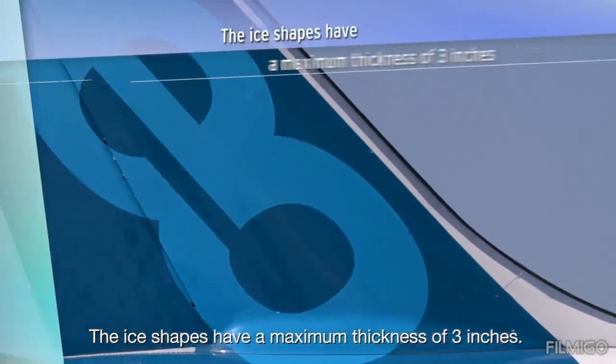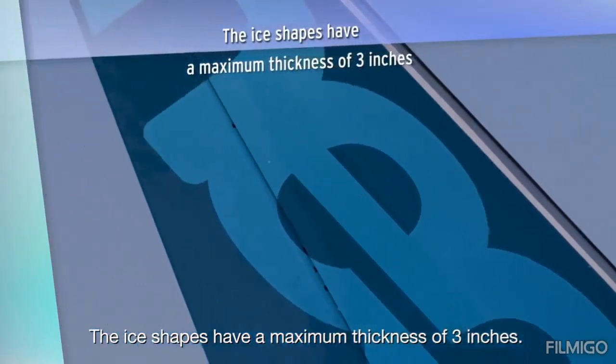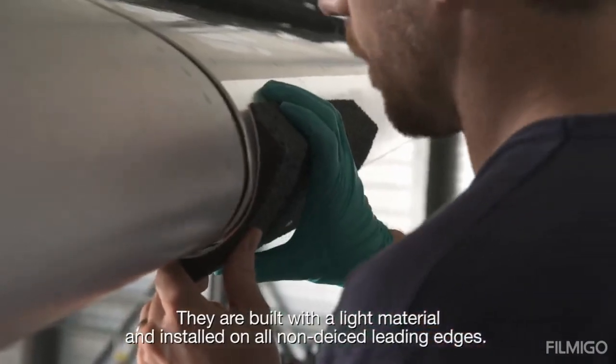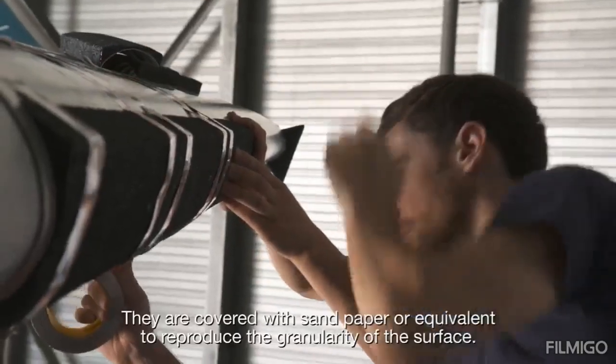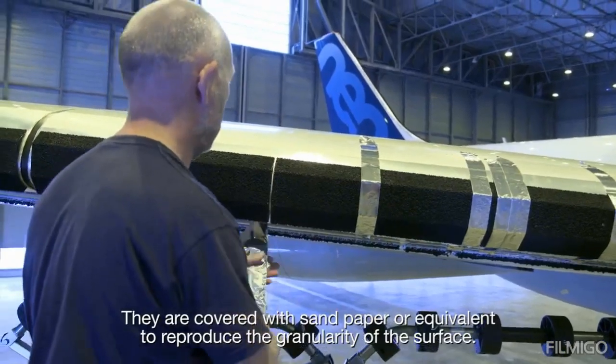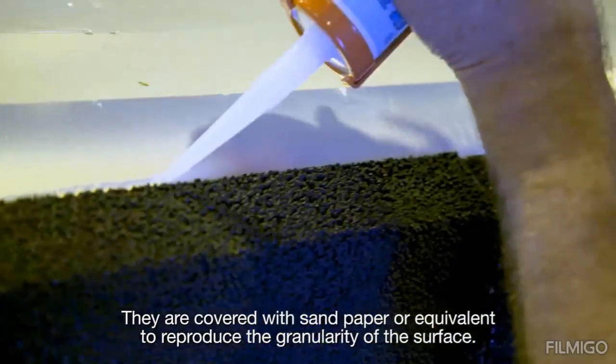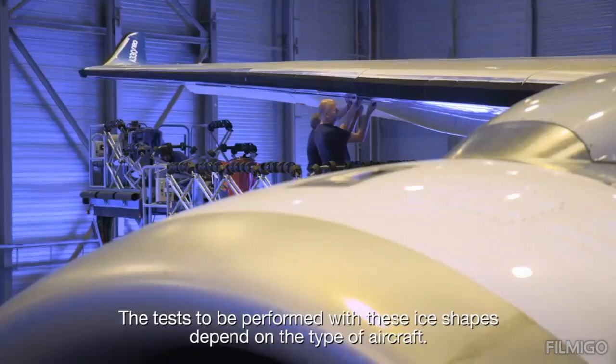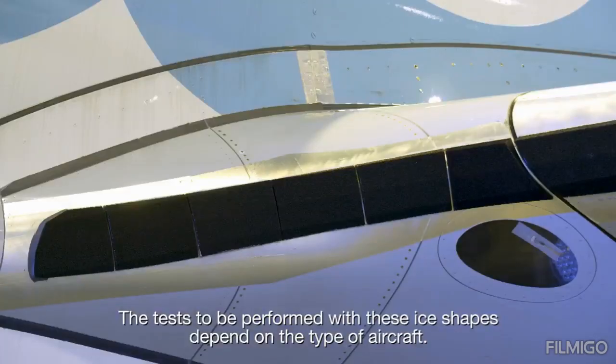The ice shapes have a maximum thickness of 3 inches. They are built with a light material and installed on all non-de-iced leading edges. They are covered with sandpaper or equivalent to reproduce the granularity of the surface. The tests to be performed with these ice shapes depend on the type of aircraft.